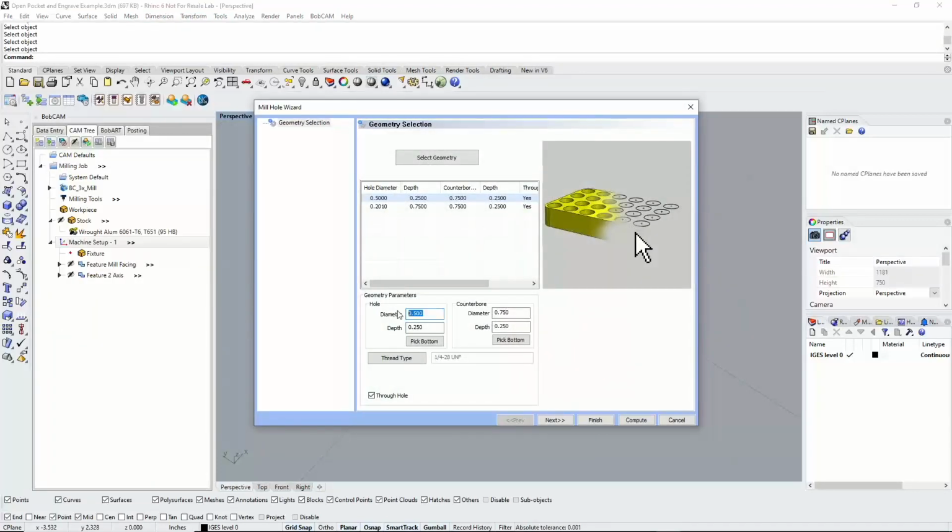And then we'll see the hole diameter is a little bit big. The depth is a little off. We'll go in and pick this stuff because the counterbore, the hole diameter should be, let's see, we'll find out. Yeah, there it is. Hole diameter is a 201. The depth is 3/4 of an inch. The counterbore diameter is 0.75, and the depth is 1/4 of an inch. So something's off here in some way. I believe it's this one. We'll find out when we run it.